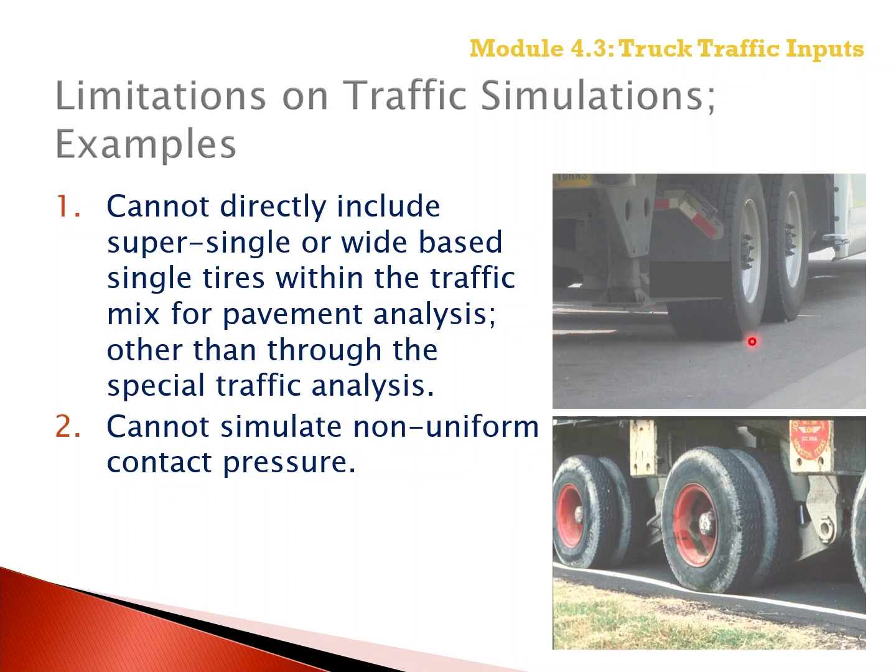This does definitely have a non-uniform contact pressure, and even with some of the standard tires where we have a dual tire on our single, tandem, tridem or quad type axles, there is a load distribution, contact distribution under that tire. That is not simulated with Pavement ME. So we use the hot inflation tire pressure to represent the uniform contact pressure.